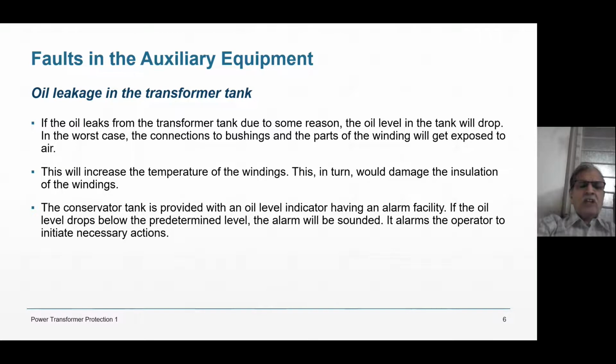This, in any case, we are going to see, but oil leakage is sensed by Buchholz relay only. It is not sensed by any electrical relay. So Buchholz relay is a must, very essential in any power transformer, right? It is not there in distribution transformer, but power transformer it is always there.